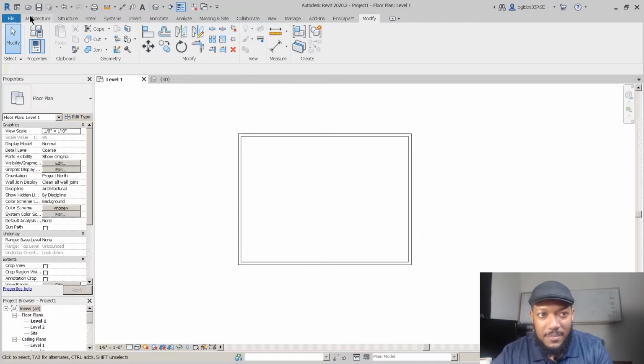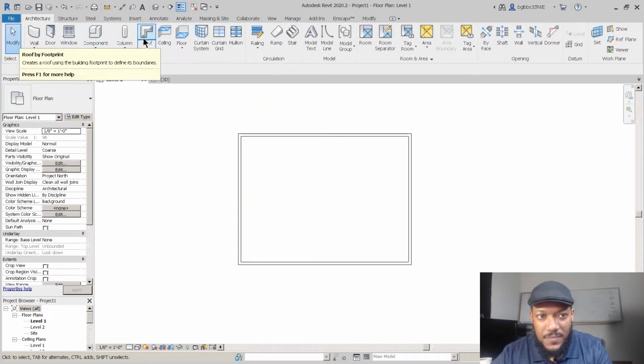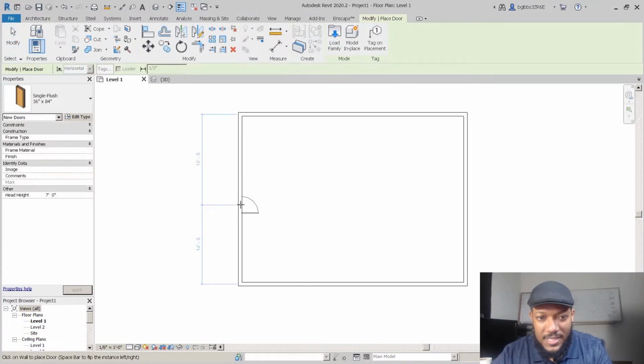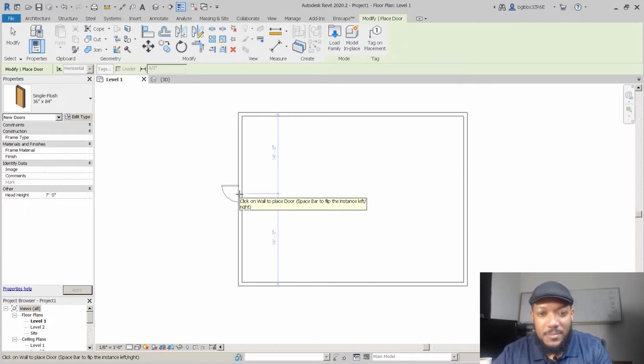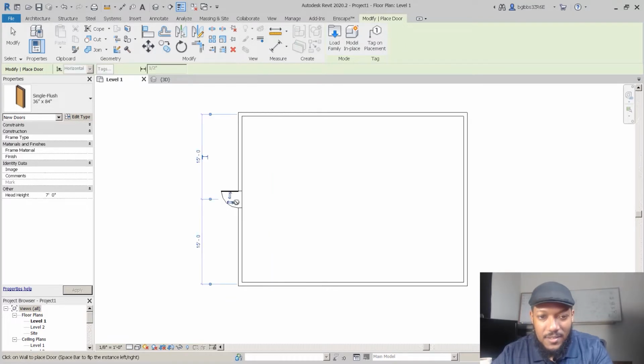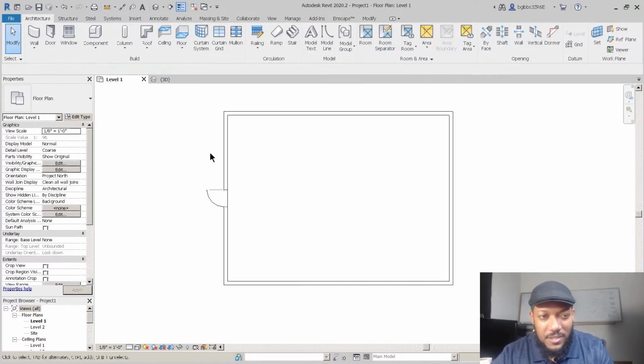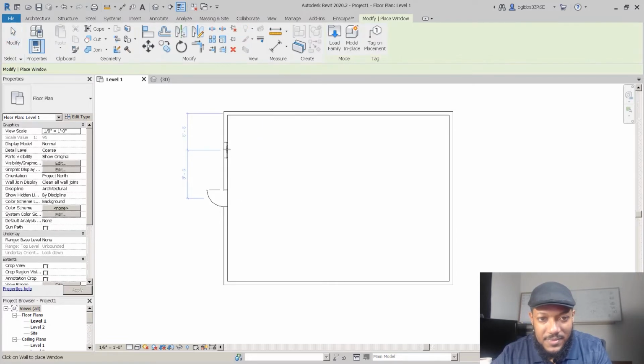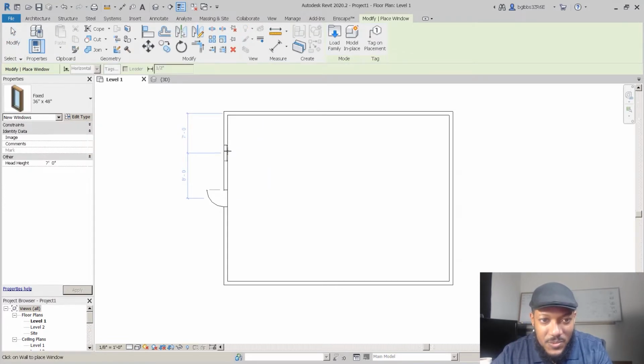And now let's go ahead and make a few doors. We're going to make a door. And as we're starting to place things, you notice that we already see dimensions. We saw that when we were making a wall, but now we can get something centered, and we could also click to make a window, and you have that same sort of thing where it gives you a center.